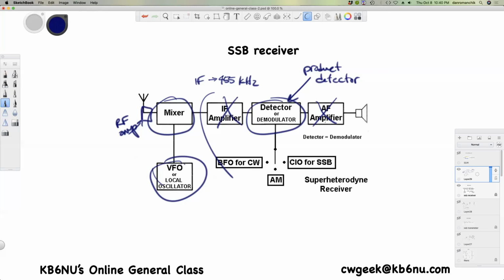If I understand this correctly, breaking this into two parts means the front end could be AM, FM, whatever, but you only have one single back end to process all those signals once you've got them out of the first stage. Absolutely. Okay, good, thanks. So all the frequency-specific stuff is here, and everything after that is all 455 kilohertz.